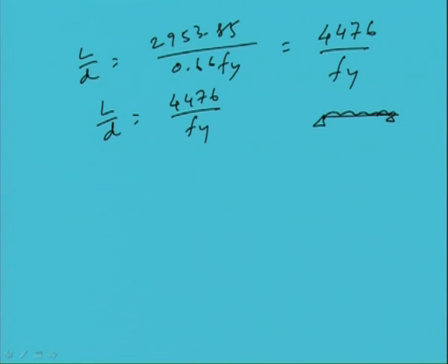Now if L by D is less than this 4476 by Fy, then deflection is not a factor. So, the stress governs the design.